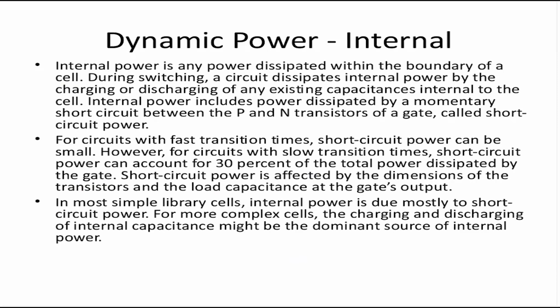So internal power is a more generic term. Short circuit power is a type of internal power. Internal power, by definition, is any power that is dissipated within the boundary of the cell, inside the cell, not dependent on the load capacitance, right?